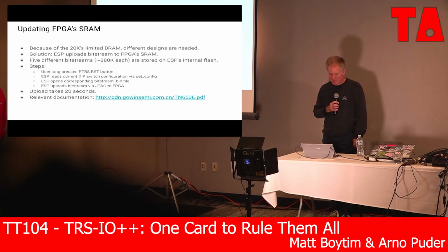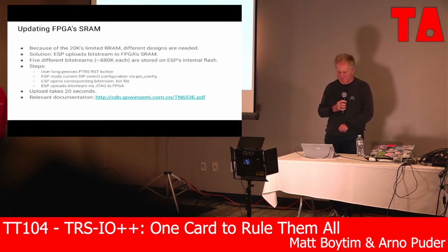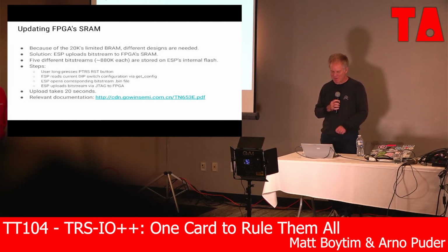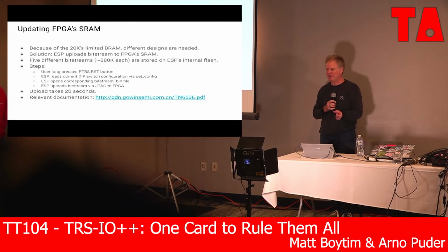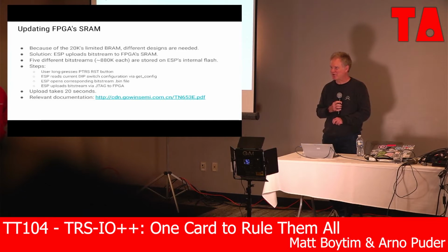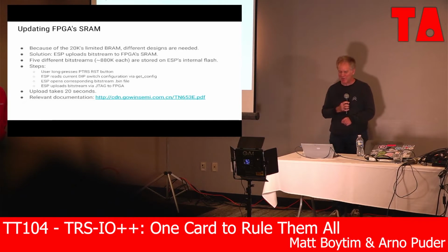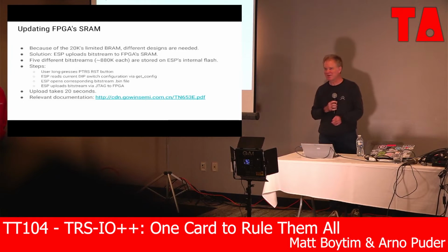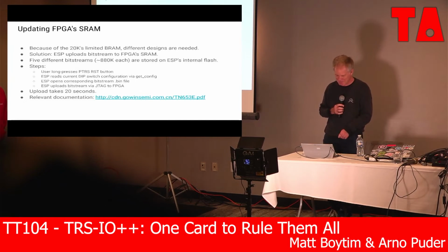Basically the way you do that is, with the dip switches, you say what mode you want, and then either you power cycle or you long press one of the buttons on the board. Then the ESP uses the SPI interface to retrieve the buttons that are connected to the FPGA, and then it opens the bit stream. The bit streams are stored on the ESP's internal flash, so you don't need an SD card or anything. It uploads it, which takes about 20 seconds. It's a little bit inconvenient, but okay, 20 seconds.